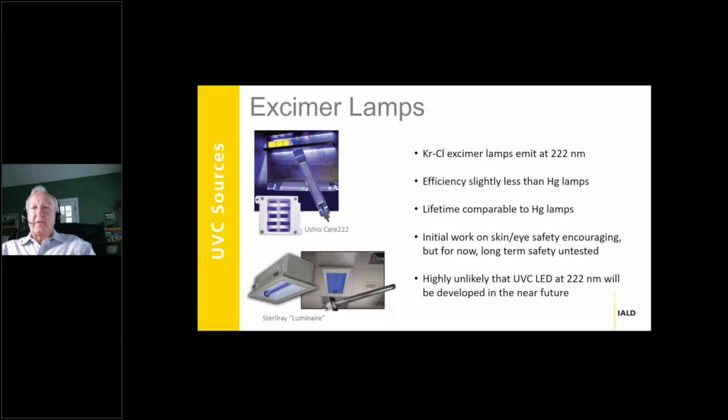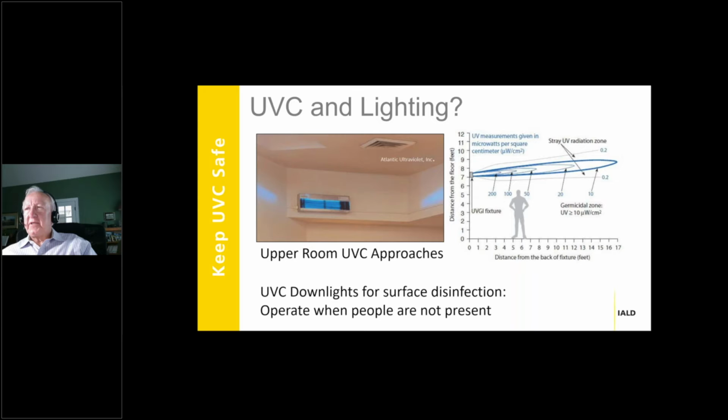Now, in my final slide, I just want to show where some UV systems have typically been used in room disinfection, actually since the 1950s. What you see here on this slide is probably one of the earliest applications of UV germicidal disinfection in the built environment. Now, remember we've talked about how UVC radiation can break DNA molecules, how it can damage other kinds of organic materials in the built environment like polymers and paints and fabrics. Similarly, it can be damaging to human skin and eyes. And as a result, it's typically agreed that if you use UVC radiation, you need to keep it away from people.